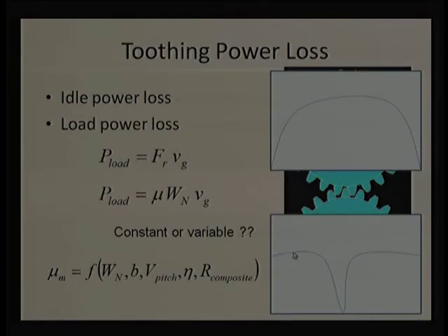That is why we need to model it properly. It should come with this kind of characteristic. Maybe initially there is some sort of undulation or variation, maybe statistical, but it will come to 0 at the pitch circle diameter when we are talking about spur gears and helical gears. Of course, when we talk about hypoid gears, in those situations this coefficient of friction will not be 0. There will be sliding, and that will cause some value of the coefficient of friction.